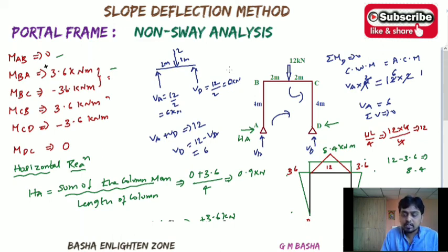I hope you understand this lecture. In the next lecture, up to here I solved both-ends-fixed and both-ends-simply-supported conditions in frames also. In the next problem I will take a problem where another beam is connected, so the sum of the moments at a particular joint becomes 0. There will be three connecting members at this joint, MCD, MCB and MCE. We have to sum these three final moments, and then only you will get 0.